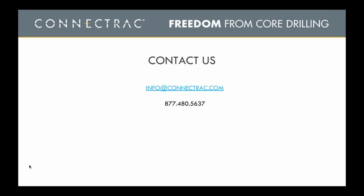We get asked that a lot. Our system has a wireway, not a raceway, it's a wireway. And in that wireway, our pre-wired power actually goes into a galvanized steel flex conduit, and so that becomes our separation. So in that wireway, you can have that pre-wired galvanized steel flex conduit and your data cables, and there's no